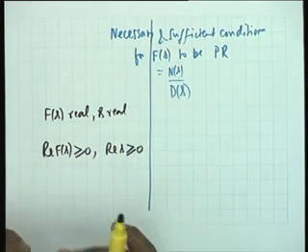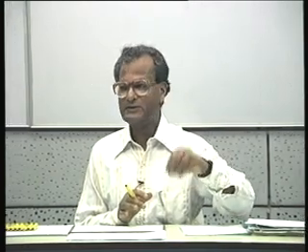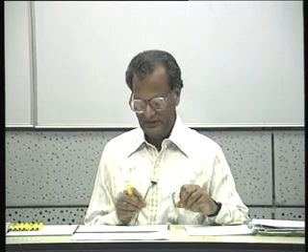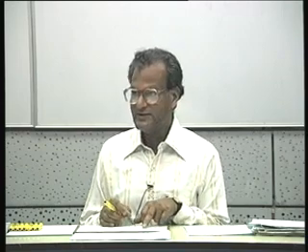Now, if we want to test a given function to see whether it's positive real or not, the definition is difficult to apply, because this states that you shall have to explore all points in the right half plane, all s in the right half plane, which is an extremely difficult task. That is, you have to put s equal to sigma plus j omega, consider all possible values of sigma and all possible values of omega. In very simple cases it may be possible, but not otherwise.